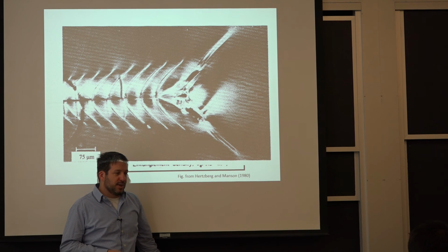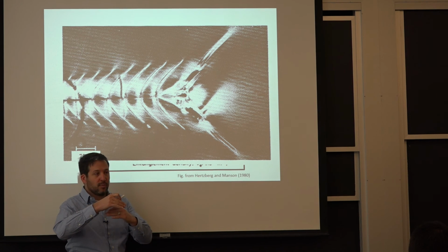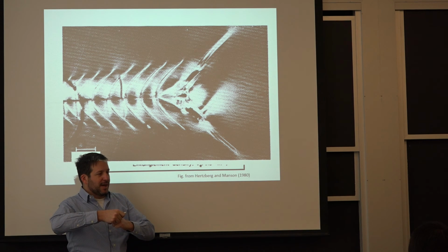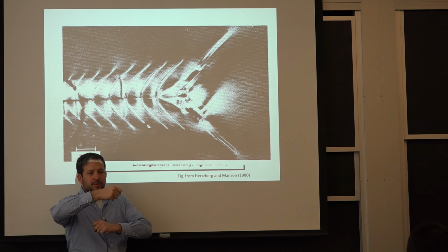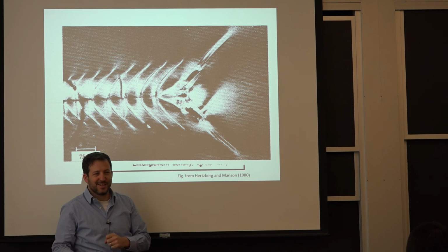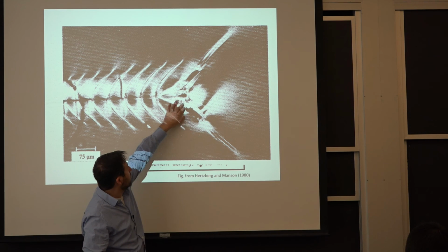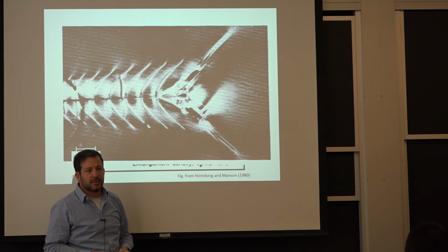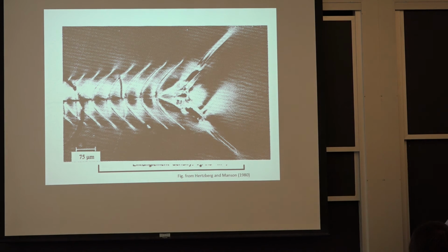But it's one of those features that is just very, very different than the crazing that we were talking about. If you have a craze in the material and you're starting to form voids, yes, you are absorbing energy to create that 1,000% strain and hold the structure, but the next step is to keep going. There's no real back and forth. And here, you can blunt the crack a lot more by deforming it in two different directions. That's why you get a lot more toughness in this case. On the two materials we had, if you remember, the one that we had to bend back and forth, I didn't bring it back, but it was the polycarbonate.